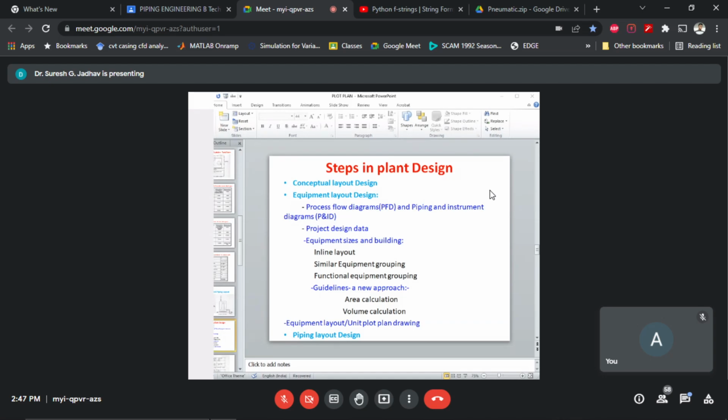So here exchangers are placed next to the towers and thermosiphon reboilers, which have large diameter pipelines attached to the boiler and tower as well. Towers are arranged with individual platforms for several in a line. Generally, surge drums, storage vessels, coolers, heaters are placed between distillation columns in the process flow sequence.